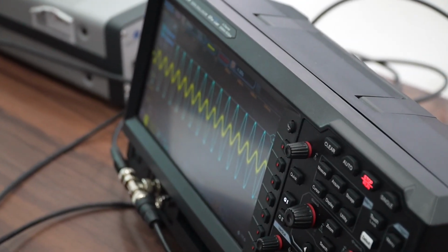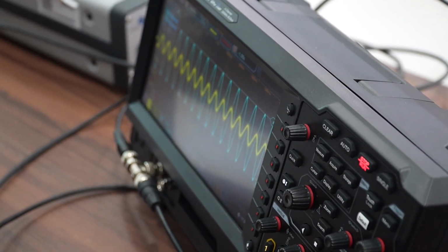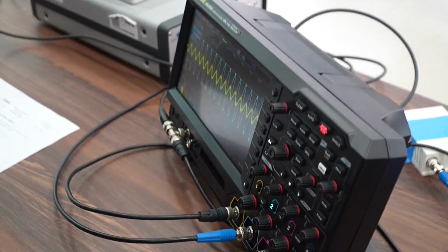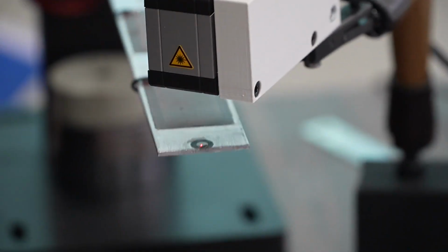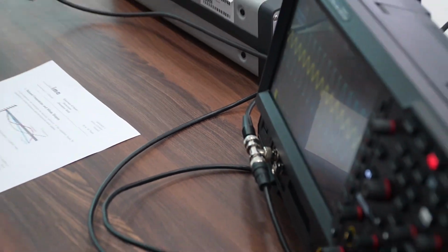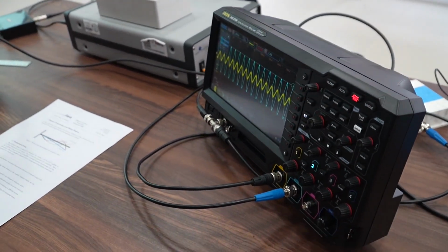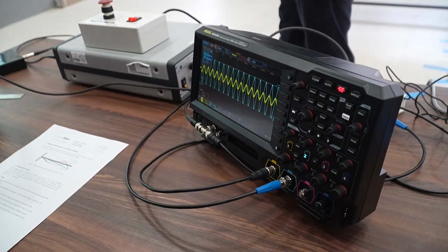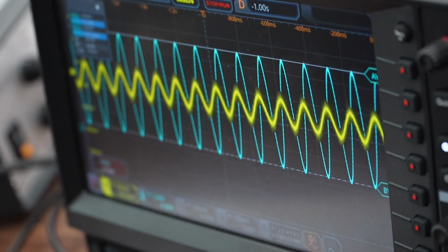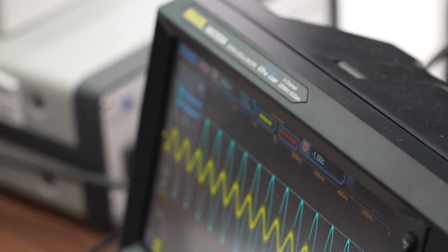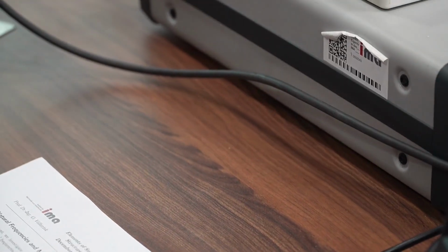And now you see, and maybe this value you can, yeah, it doesn't matter. Anyway, you see that static state 0, first eigenmode tip deflection 4.25, second mode tip deflection only 0.12 millimeter. So the higher the frequency goes, the smaller the deflections will probably be. Okay? Now what you could do is, now you do the same thing here, here, here, and here.